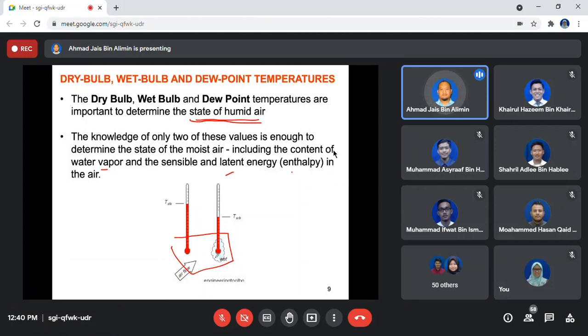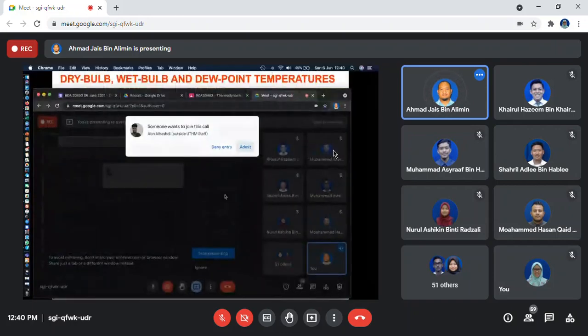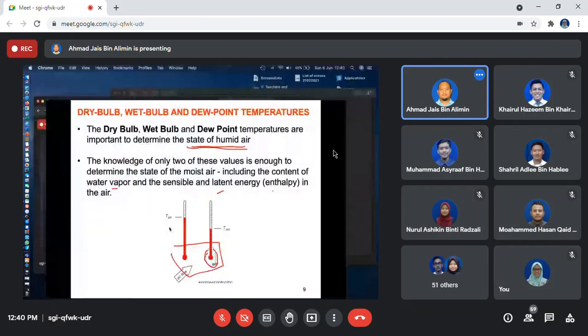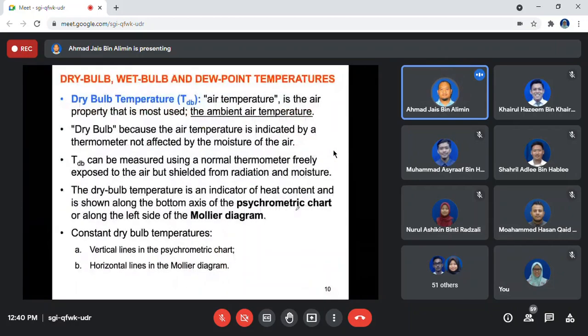So for the wet bulb, we physically trap a bit of moisture at the end of the thermometer, whereas for the dry bulb there's no insulation, there's no medium, and the end of the thermometer is simply in contact with the incoming air. So for the term dry bulb, when you write it down, make sure you put it with a dB subscript, or we call it the air temperature. Basically the reading for the ambient air.